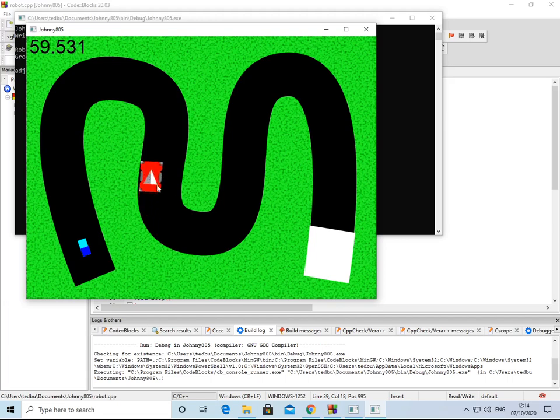What it also has on its four corners are these color sensors. So what they're reading is a kind of numerical value which represents the color of the ground underneath that corner of the robot. So that's how the robot is detecting where the edge of the road is, and the computer program that we write for it is going to use the four numbers that it reads from those four sensors to make a decision over and over again very quickly about what the motors need to be doing at each point in time. And that's what the code is going to do.